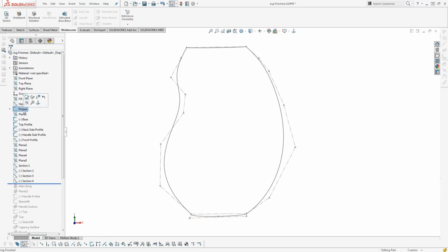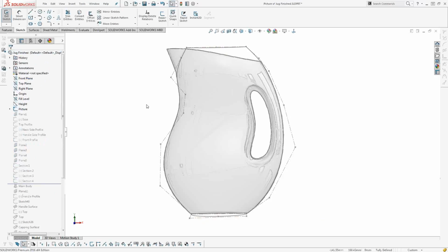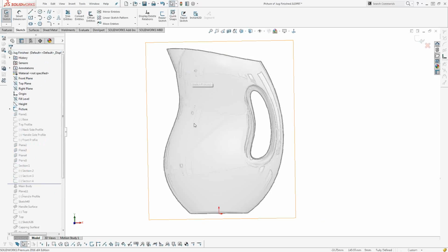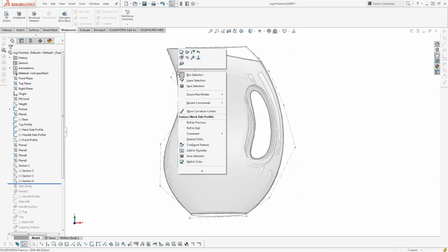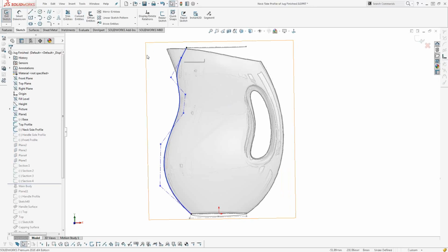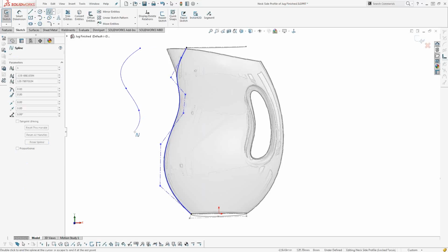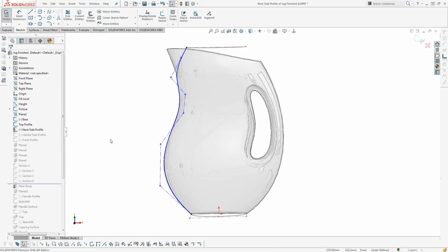And so, for instance, we've got this little sketch that's done over here. Okay, someone drew this up and brought it into the system, and we're going to go ahead and trace over it. The new addition in SolidWorks 2016, though, is that they've included new spline types within SolidWorks. So besides being able to come in and draw out just a regular spline that we're used to, there's a new spline type in town now.